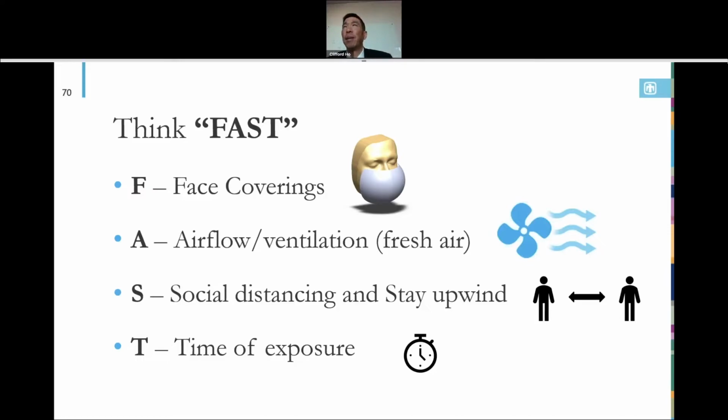Many people have moved to a hybrid or telecommuting situation, but they are having kiosks, landing sites at work. And I think the same general conclusions apply. You want to, if you can, ensure your ventilation is such that you've got more of a through flow or once through condition, as opposed to the conventional well-mixed condition with lots of diffusers, lots of return vents.